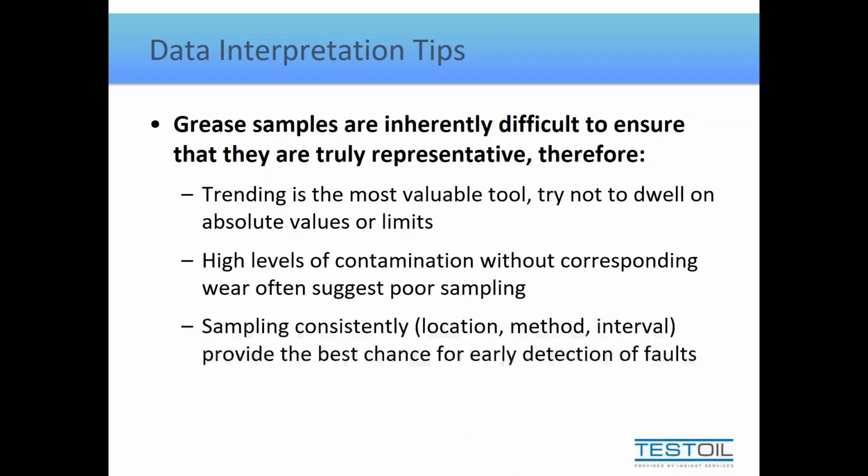So like I said, make sure you try and take those samples as consistently as possible, meaning consistent location, consistent method, consistent interval. That will give you the best stab at trending your results and seeing any significant changes and helping identify if you have a contamination issue, if you have a wear issue, if the greases are beginning to break down, anything like that.